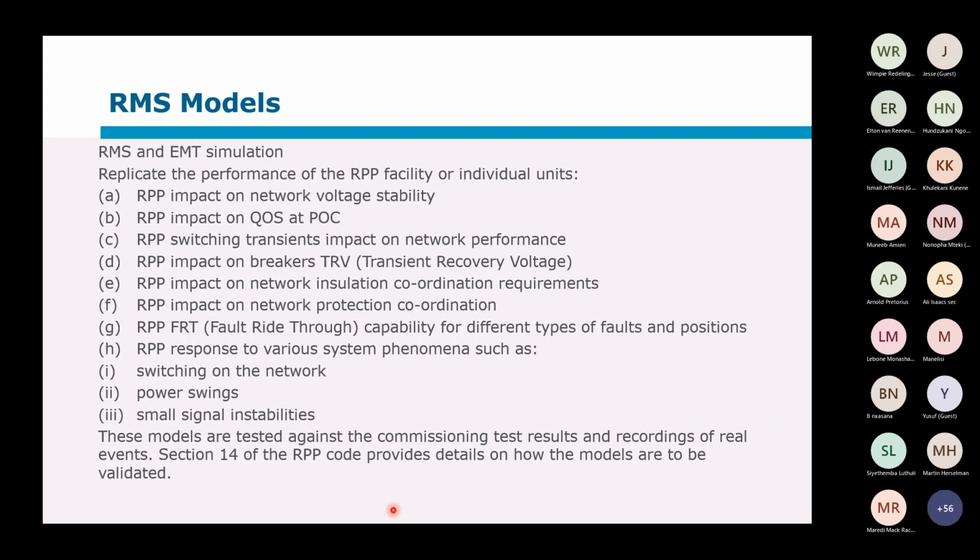Each generator that trips at this point in time brings our system closer to instability, where the frequency will drop too far and all the generators can trip off. And typically the renewables don't really support the network quite as much as we want.